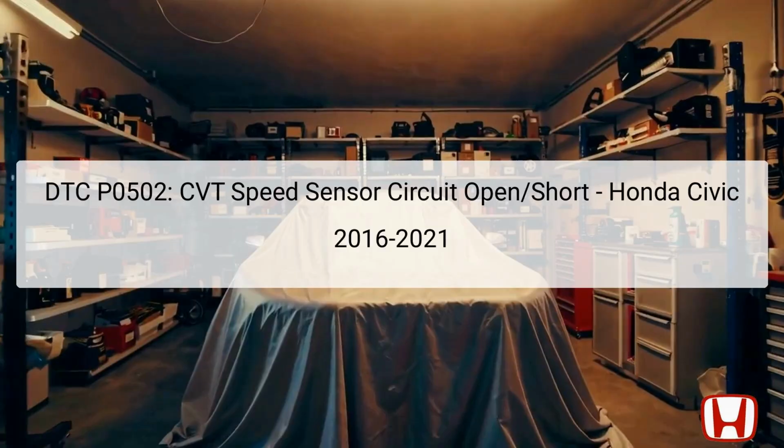The DTC P0502 indicates a problem with the CVT speed sensor circuit, specifically relating to an open or short in the electrical circuit. This DTC is critical as it affects the vehicle's transmission performance. The CVT, or continuously variable transmission, uses the CVT speed sensor to monitor the speed of the transmission and relay this information to the Transmission Control Module, TCM. If there is a fault, it can prevent the transmission from operating properly.